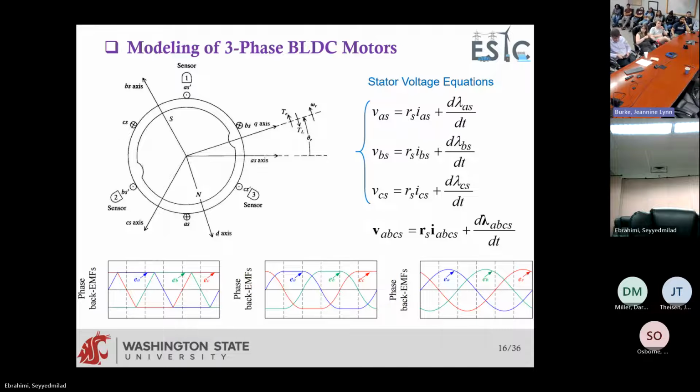If you rotate the shaft, they can be sinusoidal 3-phase voltages induced. They can be like this, what we call quasi-trapezoidal or pure trapezoidal. So if you buy different machines, they come in different ranges. I've seen a lot of machines like this or like this. It all depends on the structure and how they're manufactured. So you can assume that they're sinusoidal for simplicity.